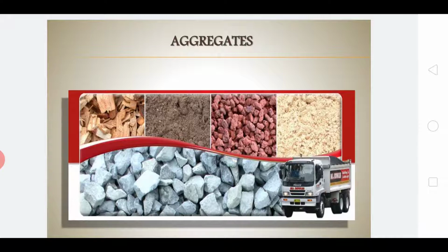These aggregates used in various pavement layers have to bear a different magnitude of stresses due to a wheel load, especially with respect to pavements. The aggregates of the pavement surface, especially surface courses, have to resist the wear due to abrasion action of the traffic, that is, when the vehicles come in contact with the aggregates, that is wear, and deterioration due to weathering, and the highest magnitude of wheel load is transferred through these aggregates.